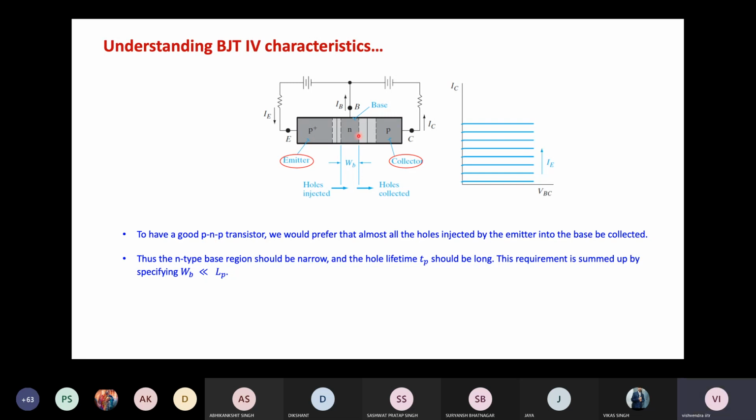But now this junction is not alone. There is an emitter as well, and this emitter is injecting current into the base, which means it is now increasing the minority current in the base. So that's why there is a net minority current because of the IE current.